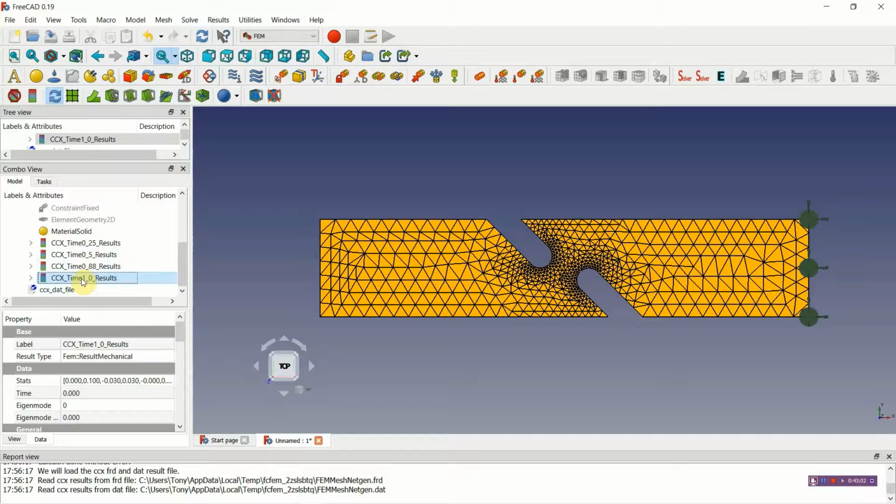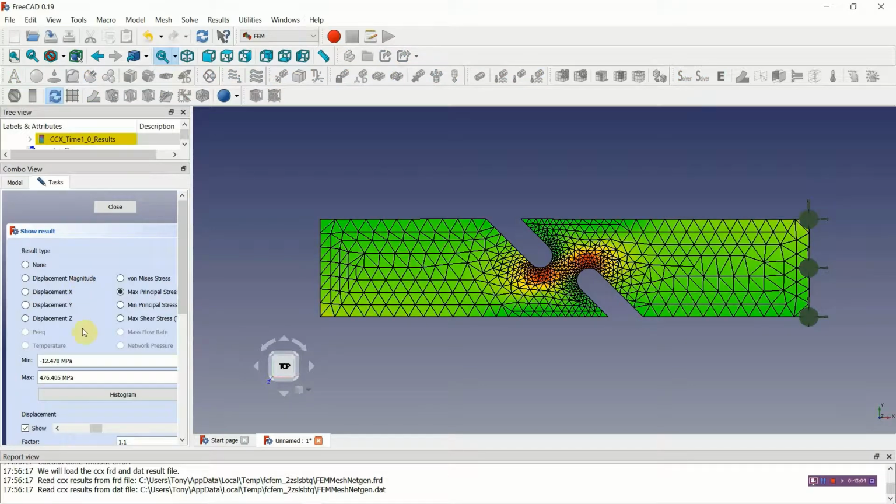I'm going to open this and we can see, for example, maximum von Mises stresses now. We'll look at a contour plot in a moment, but you can see the results are very different to before. This should be a fully plastic region now existing in the model. We can see the minimum. There's some small amounts somewhere. Well, these small amounts were probably in this region here, I suspect.